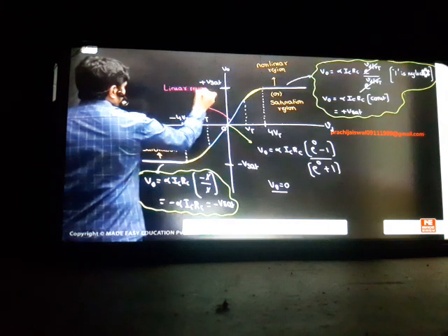There is one more region in the class, this blue line. We call it the linear region, or we can also call it the active region. This portion you can use for some applications. The blue line you can use for linear applications because output is proportional to input. When you cross 4Vt or minus 4Vt, the output is not responding. It's a saturation voltage, which is considered non-linear.